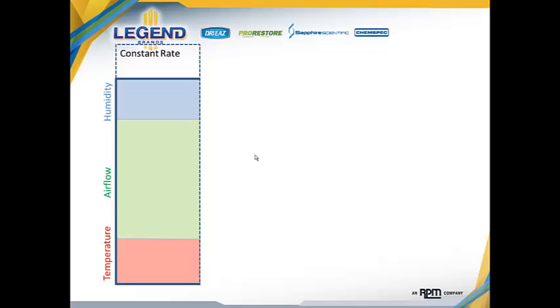The calculation that we just looked at showed us that airflow was a multiplier in terms of the drying rate if the air was in direct contact with the water. Now the problem is that as we begin to dry buildings, it's easy to get air right on the water initially. However, once the surfaces begin to dry and the water is inside of the pores, cavities, holes, openings, and voids within the structure, the assembly, and the material, it becomes impossible to have air actually come into direct contact with the water, because now we're drying water that's trapped inside the material.